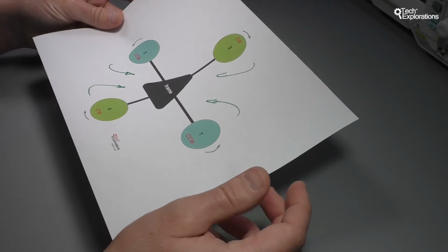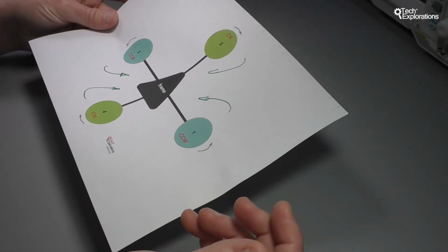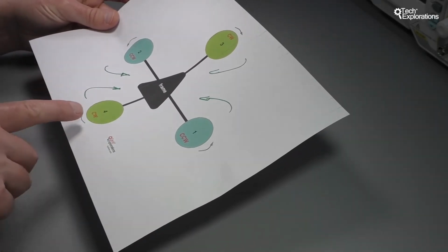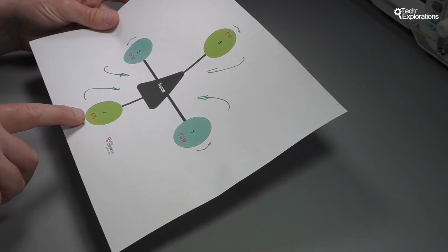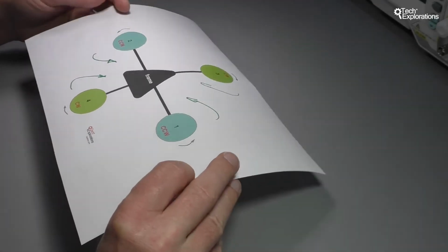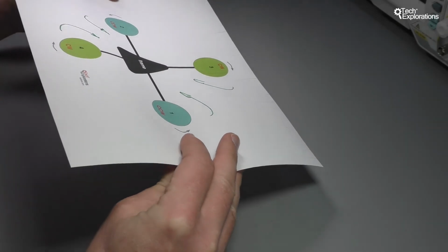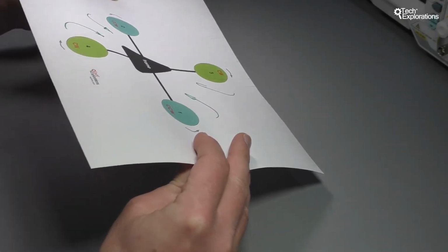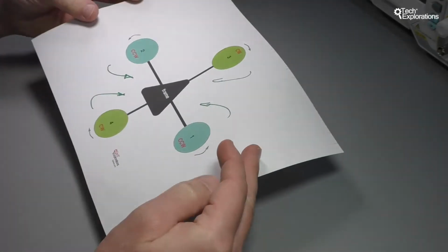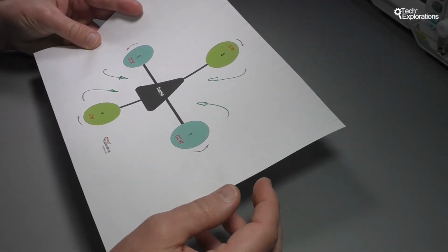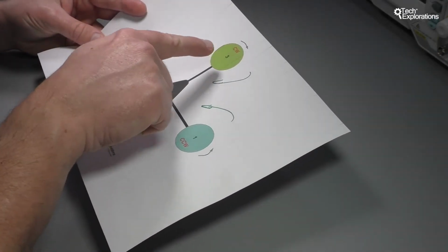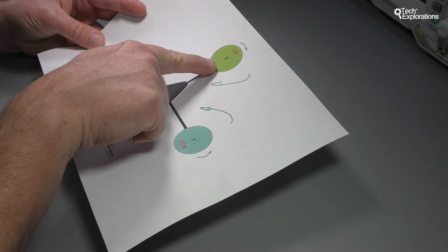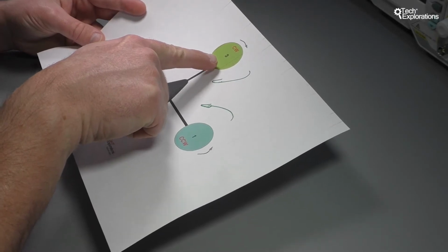So similarly, if you want your quadcopter to speed up again, to pick up speed, then what you do is you increase the speed of number 4 propeller, and that would cause the quadcopter to bank forward, and that would push it forwards as well. And if you wanted your quadcopter to reverse, then you can probably guess you want to increase the rotational speed of propeller number 3.